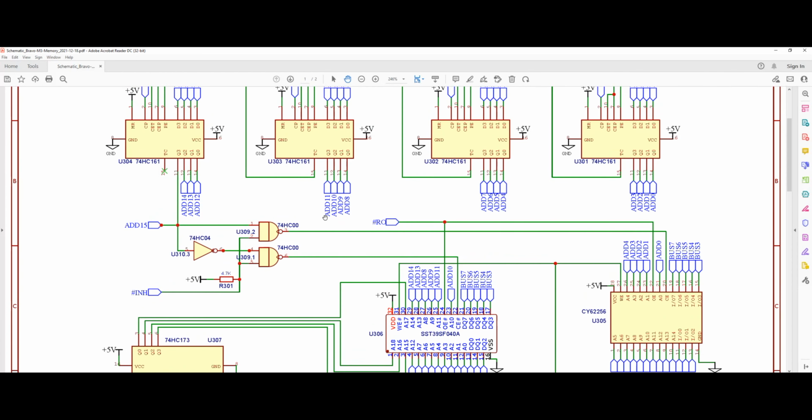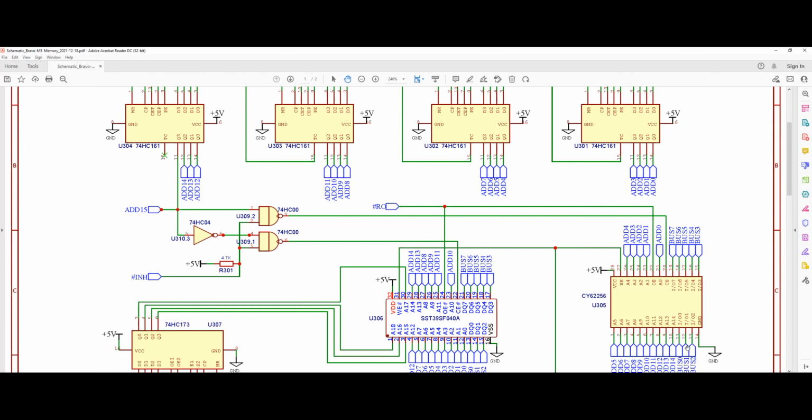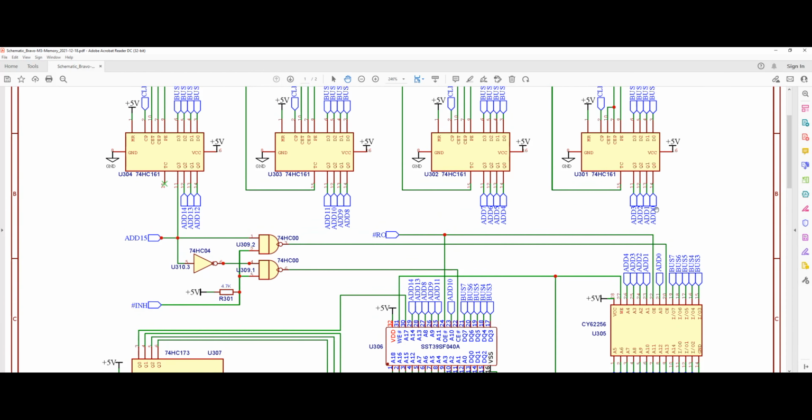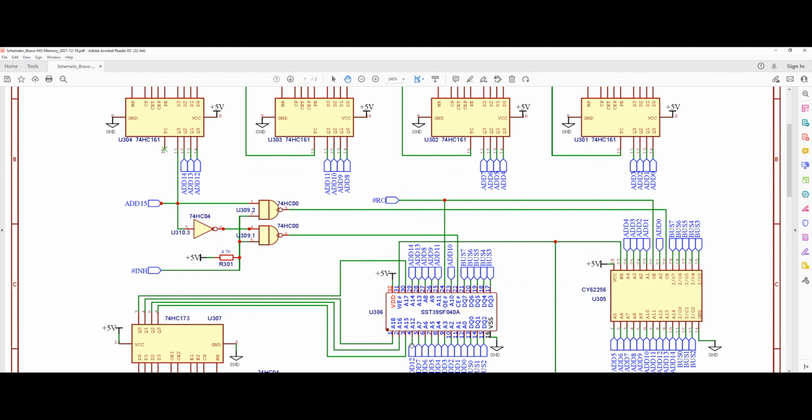That's why in this computer, when you change your memory address register to 32,768, or in other words, when we change it to 8000 in hex, then we are pointing to our RAM. If we are addressing anything below 32,768, then we are pointing to a memory address in our flash.